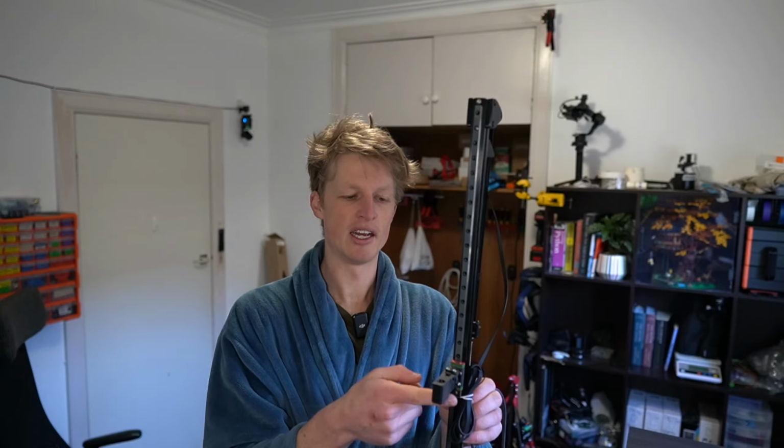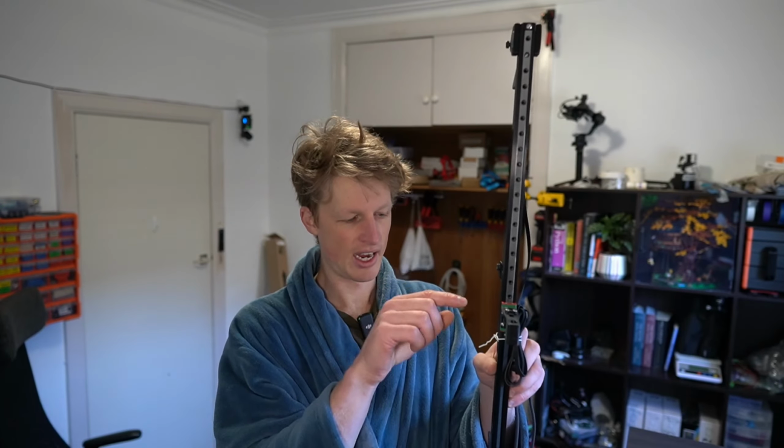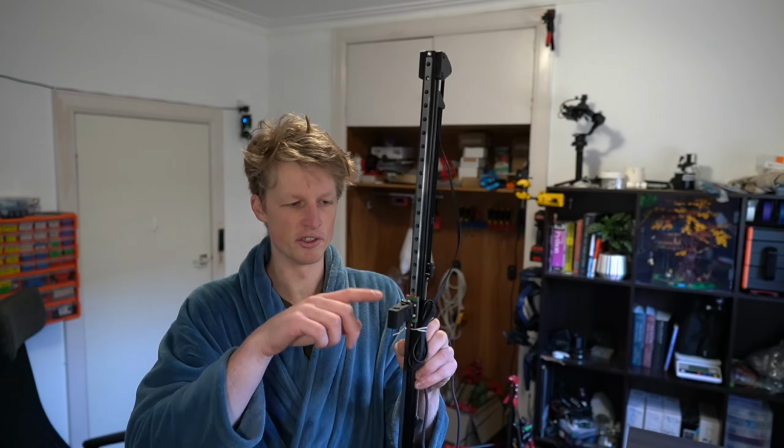So I figured I would calibrate it by having these little blocks. I've got two of these. One went up the top and one went a little bit lower. I can set these blocks in here, measure with my calipers how far apart those blocks are, and then move the slider between the two blocks. That way I can say, okay, the calipers have measured 200 millimeters apart. The slider has measured 5,000 ticks, or whatever the number is. Therefore, this is how many millimeters per tick we have. That was step one. Let's figure out how many millimeters per tick the encoder is measuring.